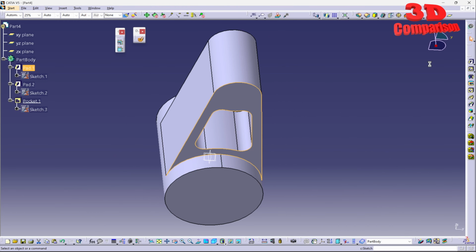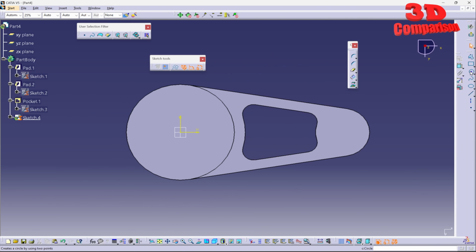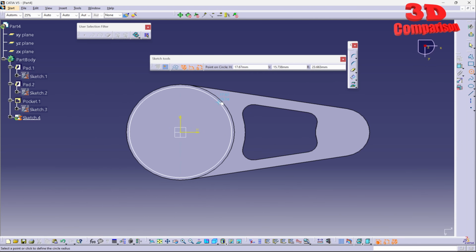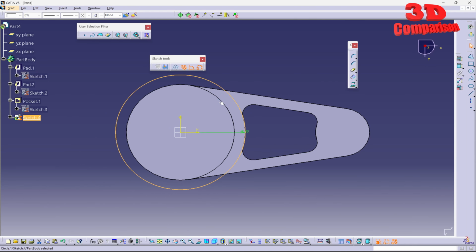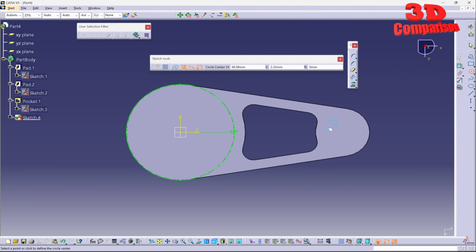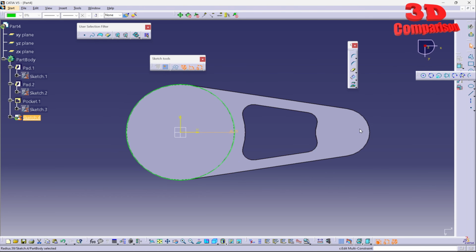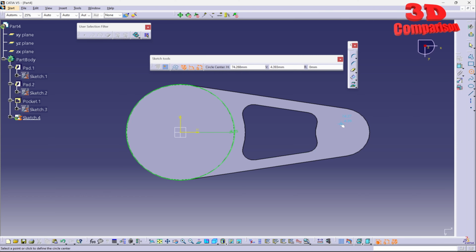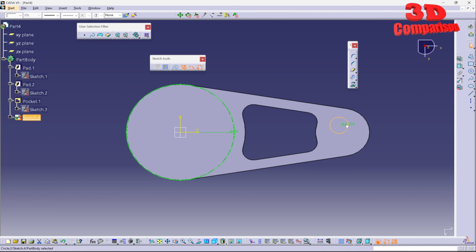And I'm going to redo the same over here on the bottom. In this case, I will just recreate those, so we are not going to use that convert for the circles. This will be 25. The other one over here, let's just recreate this. I have this set to automatically add that radius, so in this case, I will just delete it and make those coincident.